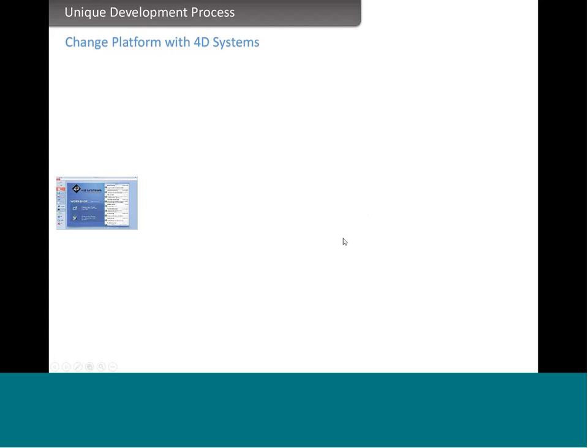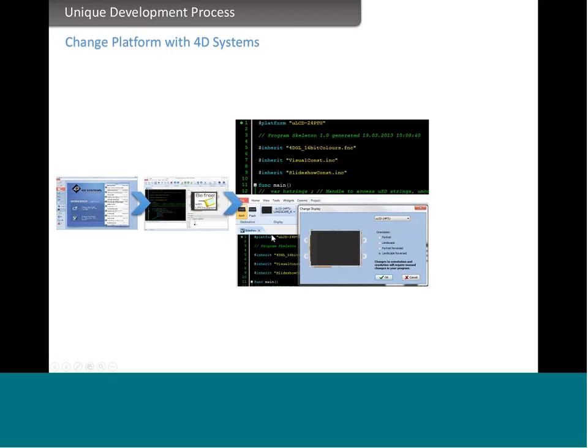So you just open the project you've done before for the old display, and then you have two possibilities to change the platform. In 4DGL code, you just have to change the first line to the display you're using. In this case, it would be the 24 PTU. You could change this here, just say 43 PT, and it will change. You have changed the platform.